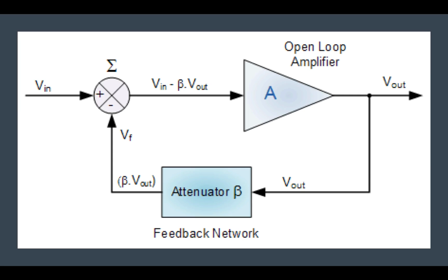The max power transfer theorem says that to transfer the maximum amount of power from a source to a load, the load impedance should match the source impedance in the basic circuit. A circuit may be a DC or AC circuit, and its internal resistance or the output impedance drives the load resistance and the load impedance. And then for matching networks, we want maximum power delivered when the speaker impedance matches the output impedance of the amplifier. And that's all I could fit